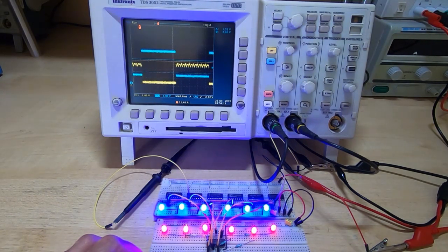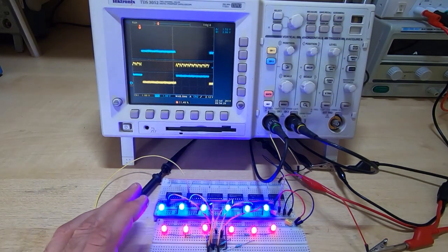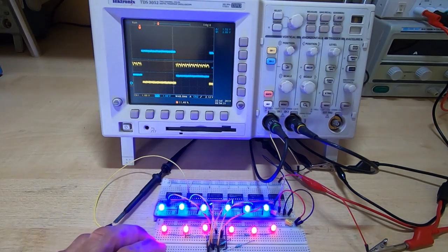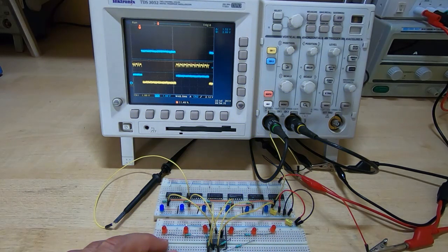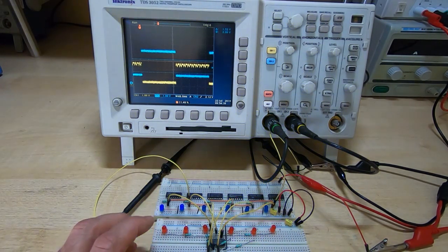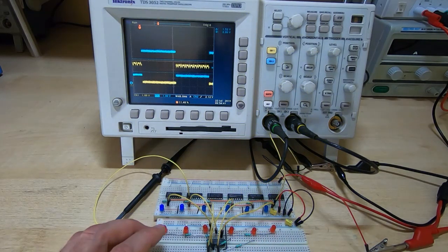And the problem turned out to be that somebody had plugged in the wrong chip type, and the output of that device was sometimes failing to properly trigger the input of the follow-on devices, causing the entire board to misbehave for a fraction of a second. And that's the sort of behaviour you can see, in that it just looks like you're getting noise or instability in the system, when in reality it's just the devices themselves that are misbehaving rather than the system.